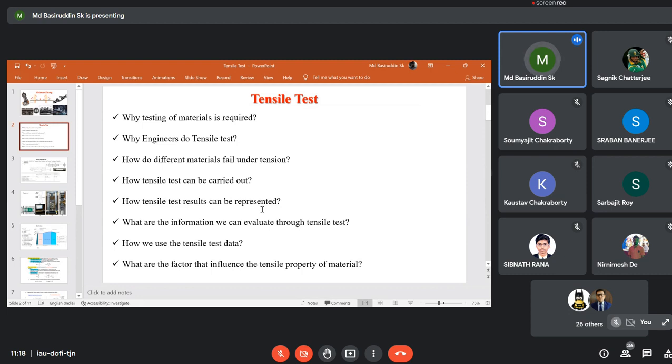If you compare the same material, then you can adjust the influencing parameters such that you get a high strength level as well as a quite acceptable ductility level. By seeing the fracture surface, you try to understand whether we need to get a fully ductile fracture surface, or an intermediate kind of fracture surface where both ductile fracture regions as well as brittle fracture regions could be there.